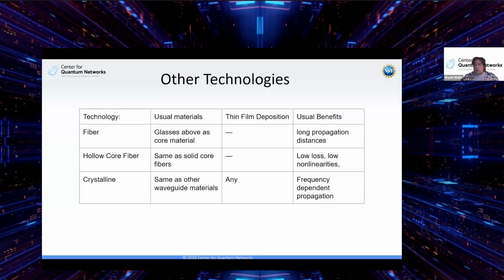The main benefit of those, and what a photonic crystal really is, think of these small nano pillars. Think of a cylindrical pillar coming out of your substrate, and think of a grid of them. Maybe they're in a hexagonal pattern, maybe a square pattern, but it's set up like how you would expect a crystal lattice to be set up. And you would see almost like a trench, a place where there are no pillars. That still has solutions to Maxwell's equations, so it still guides light.